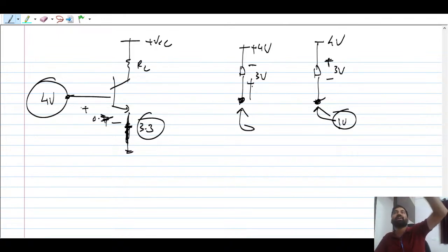Suppose we are at higher potential, the lower node will have lesser potential. If no potentials are given, we can always consider the ground as a reference for any circuit you are solving. That is very important to keep in mind. Fine, so let's move ahead.